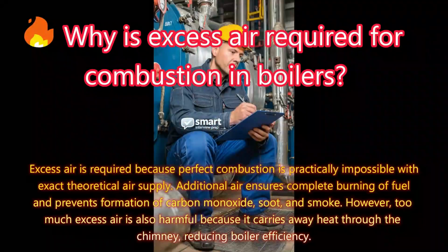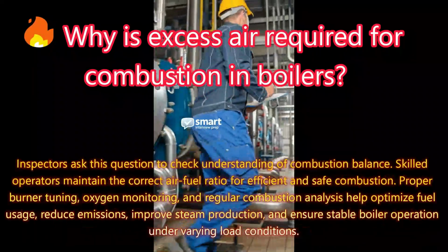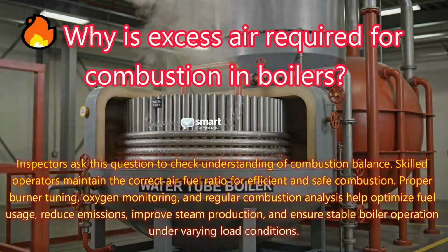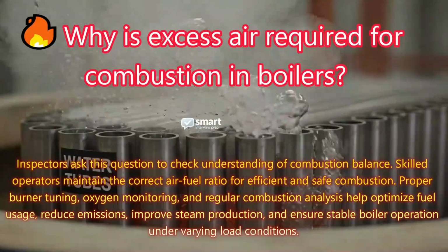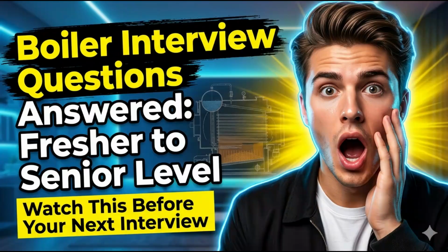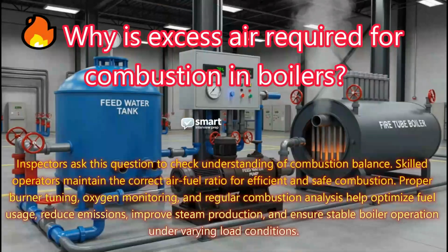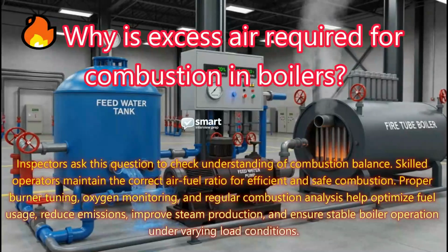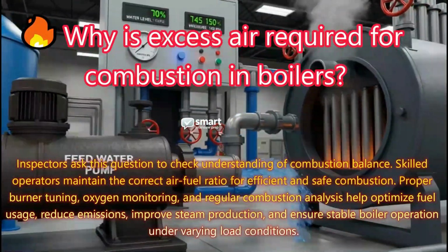Inspectors ask this question to check understanding of combustion balance. Skilled operators maintain the correct air-fuel ratio for efficient and safe combustion. Proper burner tuning, oxygen monitoring, and regular combustion analysis help optimize fuel usage, reduce emissions, improve steam production, and ensure stable boiler operation under varying load conditions.